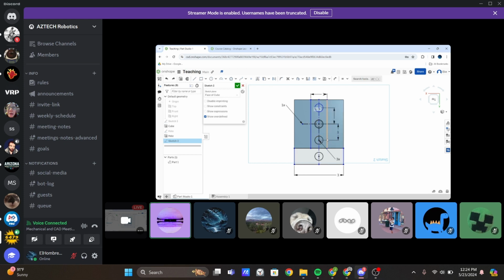So if your sketch is blue while you're drawing, it means that something is not fully defined. Okay. So these here, because this was projected from a different sketch, are fully defined because that's where the shape on the other sketches is. But these are still free to move around, so therefore they're blue. So in that case, we would want to add some more geometric relations.